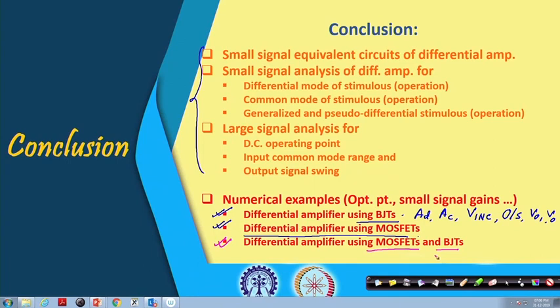Particularly what we have seen is that even though this differential amplifier's gain is not so high, the differential gain was only 8 in our example, by replacing the tail resistor RT by an active device, one NPN transistor, that helps us to really suppress the unwanted common mode signal to quite an extent, and ensures that at the output we are getting almost complementary signals.